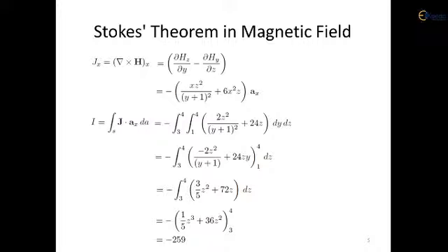So for the part A, utilizing the surface integral methodology, here we are successful to determine the total amount of the current, that is equal to minus 259 amperes here. Now you see that the minus sign here is just having the representation that the current is flowing in the reverse direction than it was initially considered. So this has to be a reversal to the consideration of the positive AX direction here as per the given magnetic field intensity vector here.